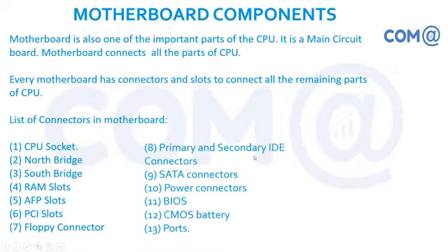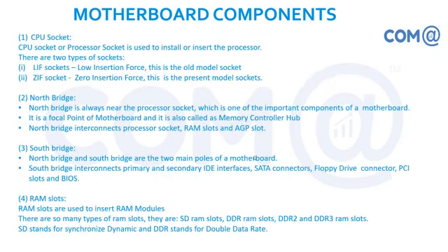Okay. So these are the main components we have seen in the motherboard. We are not going to look into all hundreds of components. We'll just see the major components, which are very much required for understanding. CPU socket. Yeah, you have different types of sockets available. Low insertion force, zero insertion force. In low insertion force, for inserting the processor into the socket, you need to apply some kind of force. A push is required, whereas in ZIF there is nothing required. Just place the processor and lock it. So that will solve your problems.